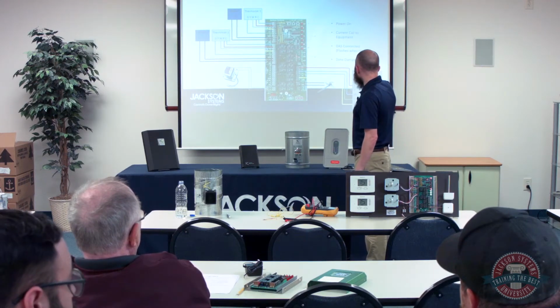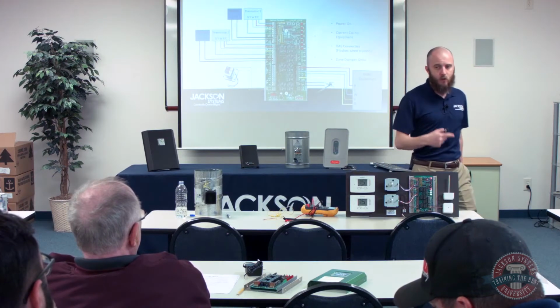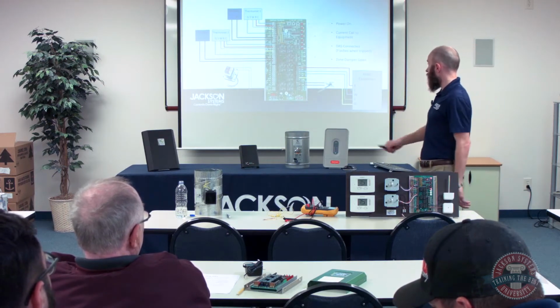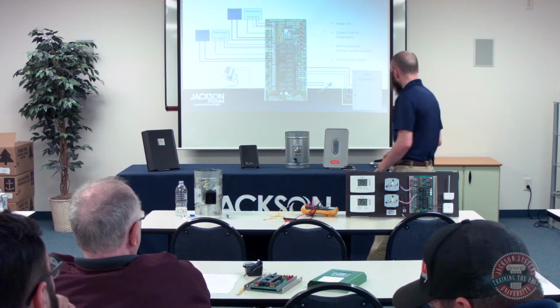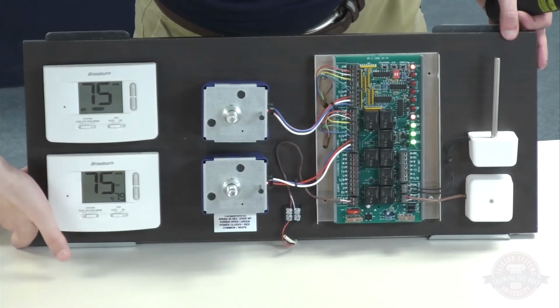So again, your damper LEDs, ZD1, ZD2, ZD3 on this one, indicate that zone damper is open. When there are no calls, all dampers are open. When we get a call, let's see if we can get a call going here.